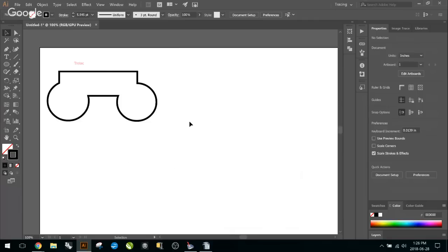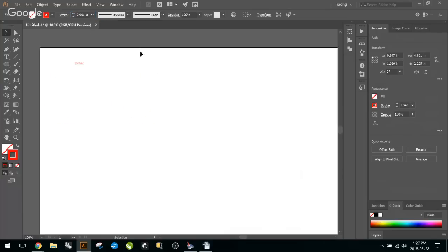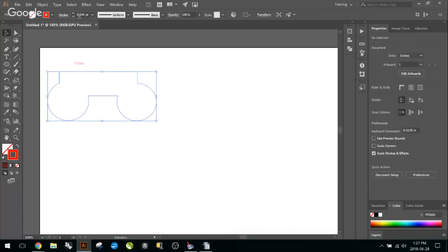Okay, so I'll just show you real quick again. Right now we'll be engraving this black box around here with our shape and leaving the inside empty. If you wanted to cut this out, you can select your new shape, and just like we did before with the text and the first shapes, select RGB red and change your stroke weight to 0.001, and I'm cutting the shape out.